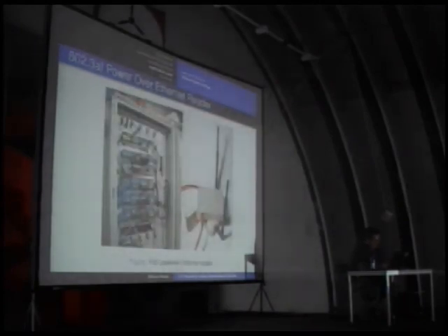These are some pictures of the installation of last year. And these are the new Power over Ethernet powered readers. You have one port where you can plug in an 802.3af complying PoE Ethernet switch, and on the other side you can see the other port, where you can cascade multiple readers.